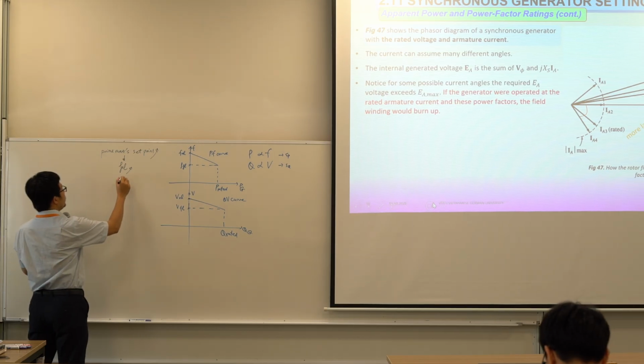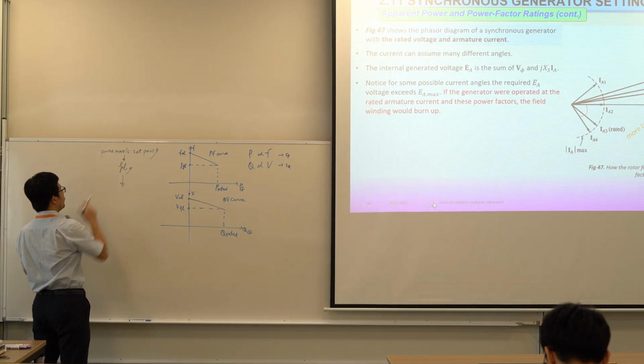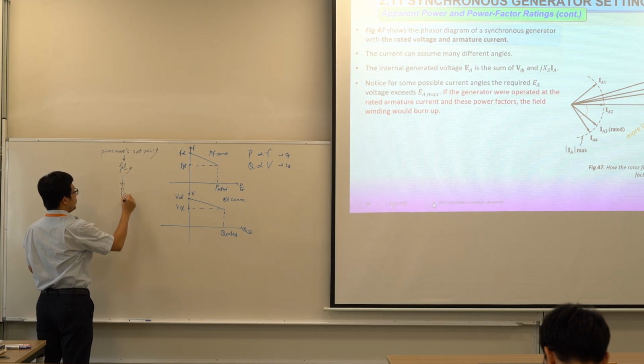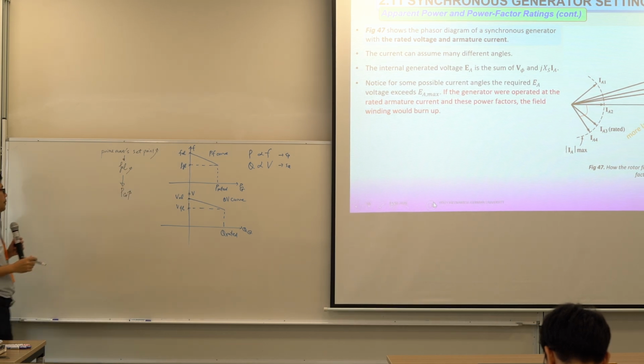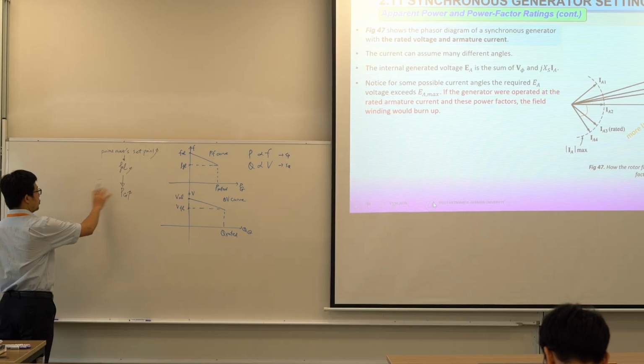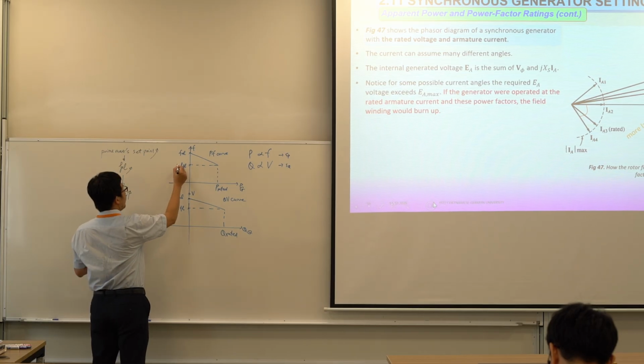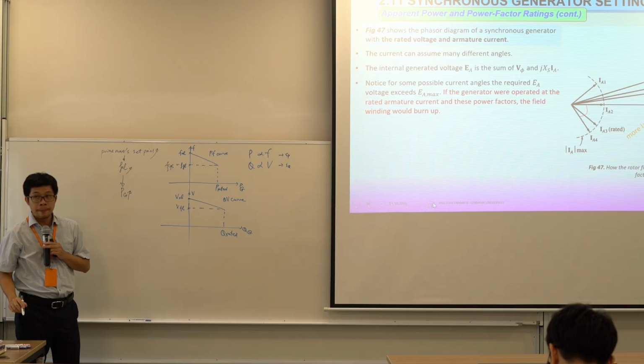So when we increase the no load frequency, that means we increase PG, that is the output generated power. That's right? For example, here we have F full load, meaning system frequency.